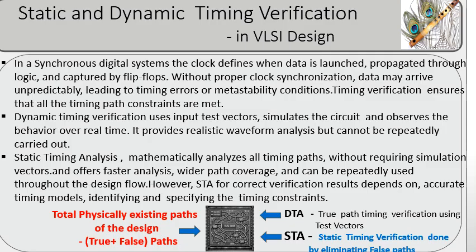Dynamic timing verification uses input test vectors, simulates the circuit and observes the behavior over real time. It provides realistic waveform analysis but cannot be repeatedly carried out. Whereas STA mathematically analyzes all timing paths without requiring simulation vectors, and offers faster analysis, wider path coverage, and can be repeatedly used throughout the design flow.